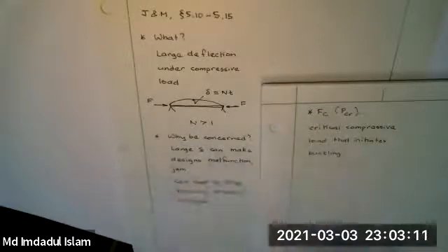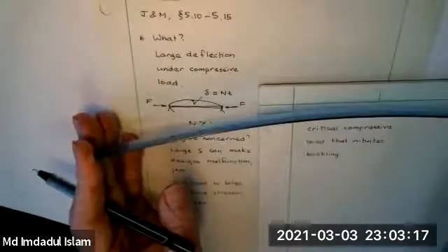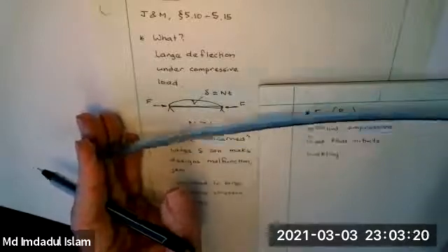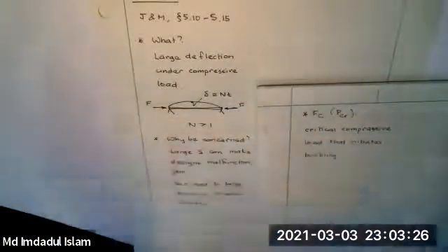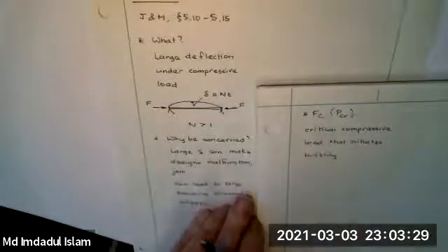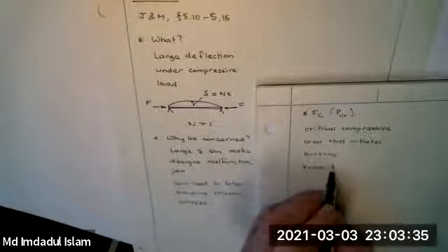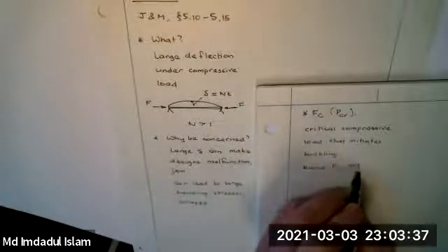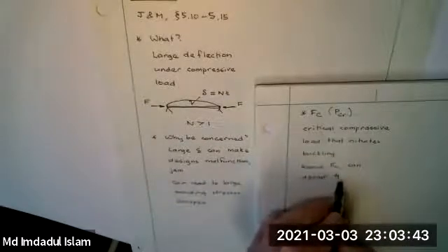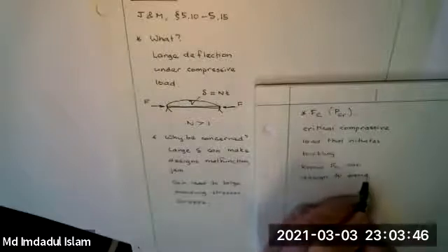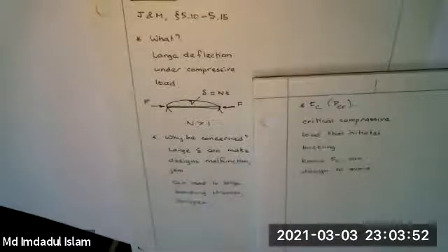When I pushed on this thing here, so you could see it, I went past that load. That's just starting to buckle. That's what the critical load is. I went further still, so you could see bigger deflection, but when it just starts, that's what FC is. If we have that, then we can design to avoid it. We can change our components so that it doesn't happen.